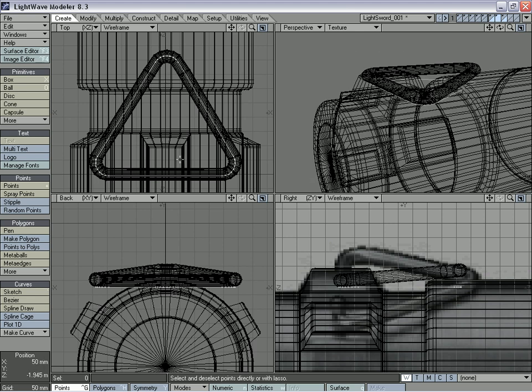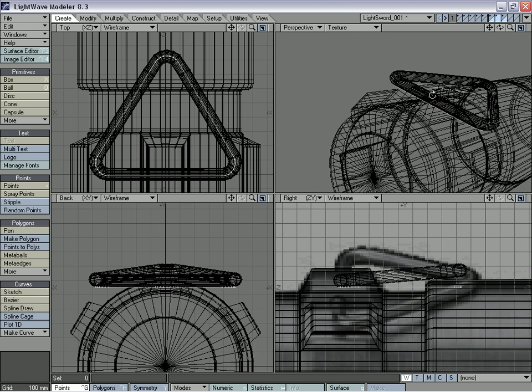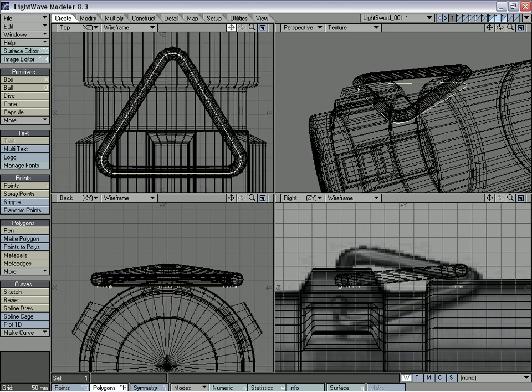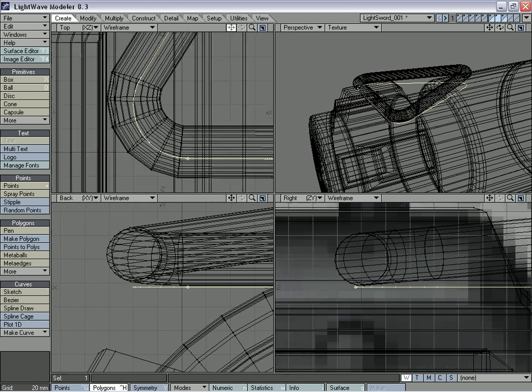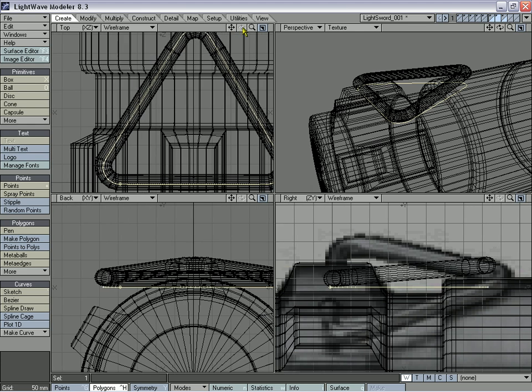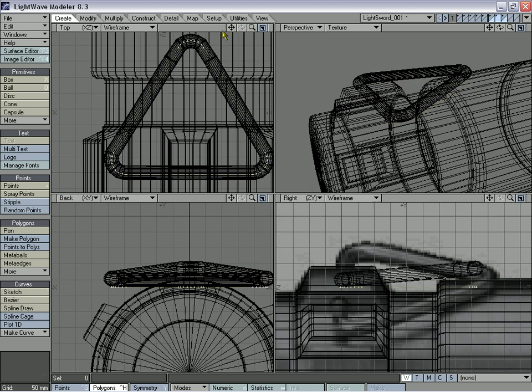But the problem with this right now is that if we're going to rail extrude this, we need to create a disk in another layer, and it needs to be aligned with the starting point of this. And the starting point is right here. And it needs to be perpendicular to this line, which is sort of curved. So what we're going to have to do is kill this spline we made,